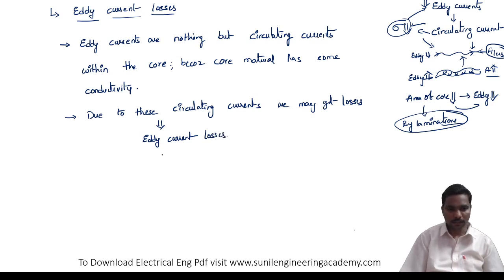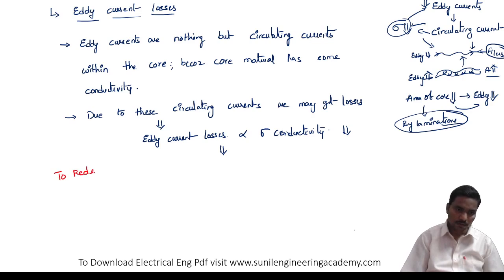These eddy current losses are generally proportional to conductivity. If the conductivity is less, eddy current losses will become less. So how to reduce these eddy current losses?